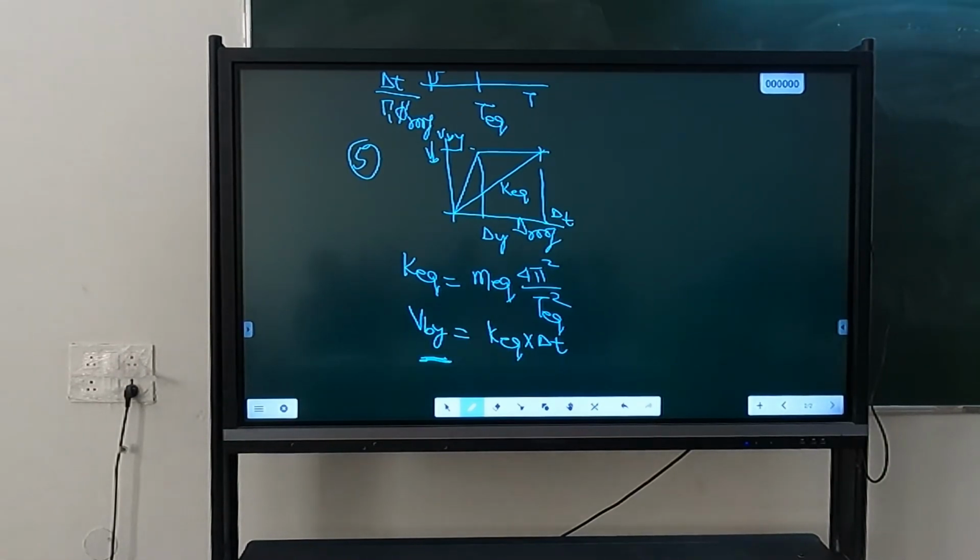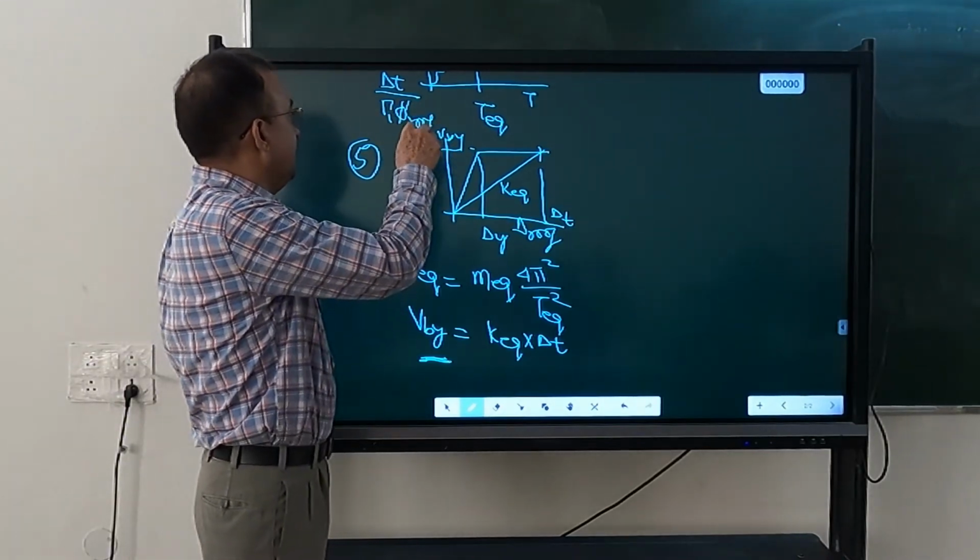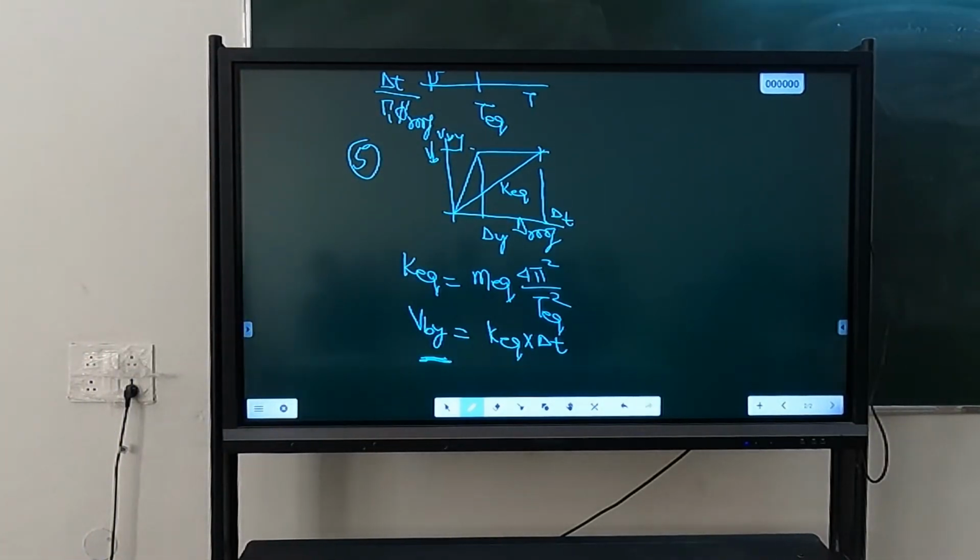So, using that, if the mode shape is same, you can convert delta T into SDT. Similarly, the mass participation will be same. The weight of the total building will be more or less same. If you are increasing columns a little bit, or maybe you are not increasing the column, you are increasing the reinforcement, so weight will not be affected much. So these are the things. Okay, so like that you can design. What is the problem? I mean, what basic difficulty are you finding?